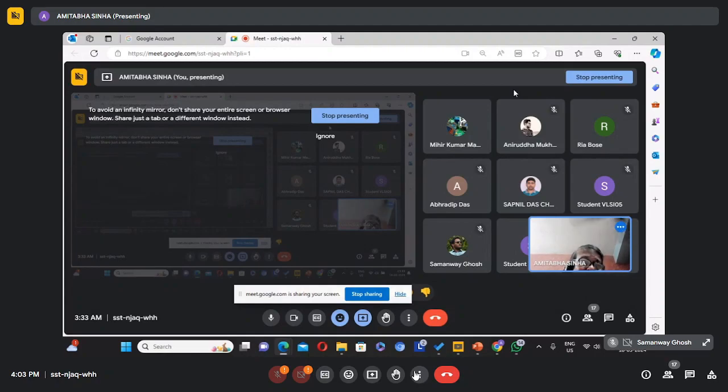The first one, after T unit of time, will give the first sample value. The second one will give the next after T by 4. Then using high speed multiplexers, you take them one after another.